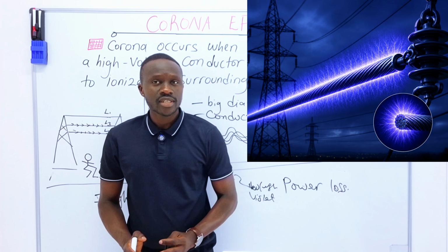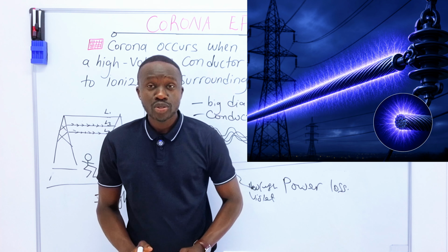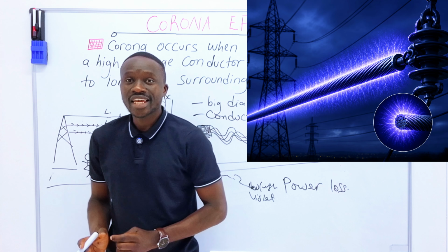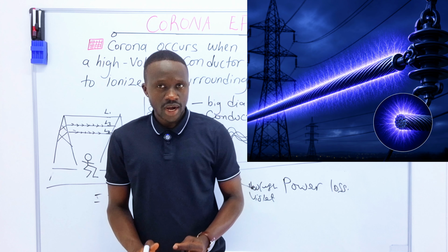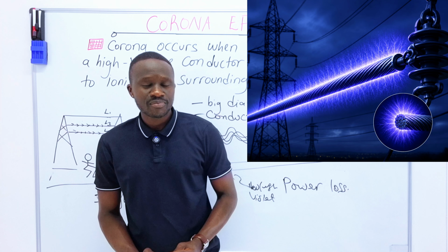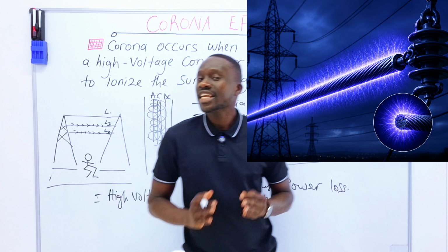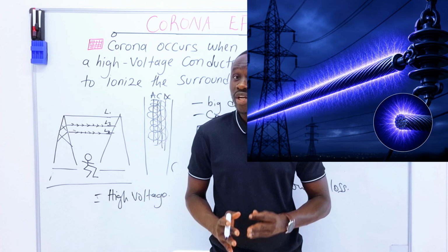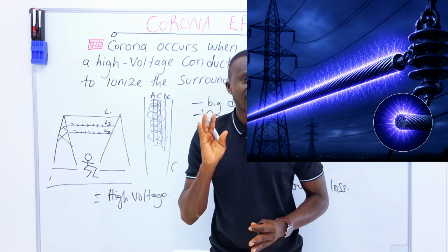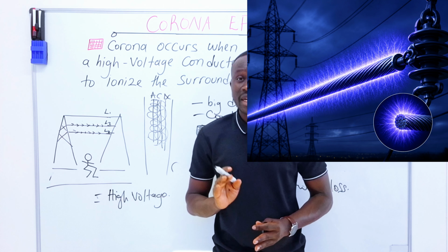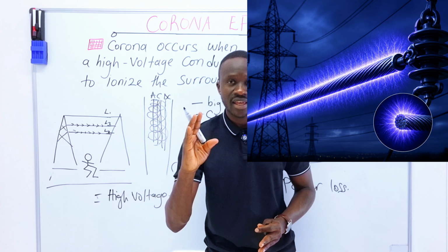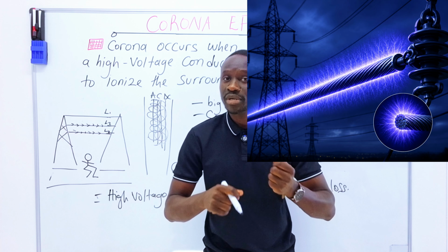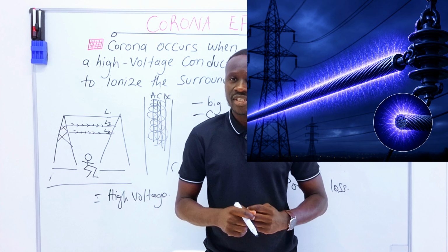A strong electric field on the cable will produce an ionization, to ionize the air molecules. And once the air is ionized with the strong electric fields, there will be a corona effect. That is when you will see that bluish color on the conductor and you hear that hissing sound like small birds. It is not like a transformer humming or buzzing, and the cable is not vibrating, it is only because of the corona effect.